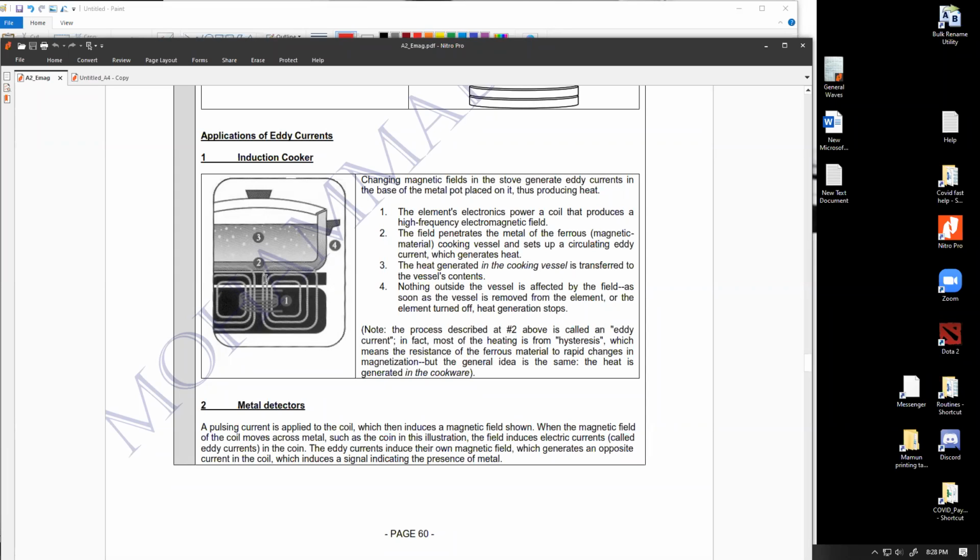For example, let's say close to the center, the variation of absolute EMF compared to ground 0 volt is, let's say, plus minus 200 volts for maximum and minimum value. Whereas on the periphery, let's say the voltage variation is plus minus 10 volt, which means for most duration of the cycle, you will always have some voltage difference from the center to the outwards, which means electrons will be continuously going outwards towards the border for half the cycle, and for the other half cycle they'll be pushed inward.